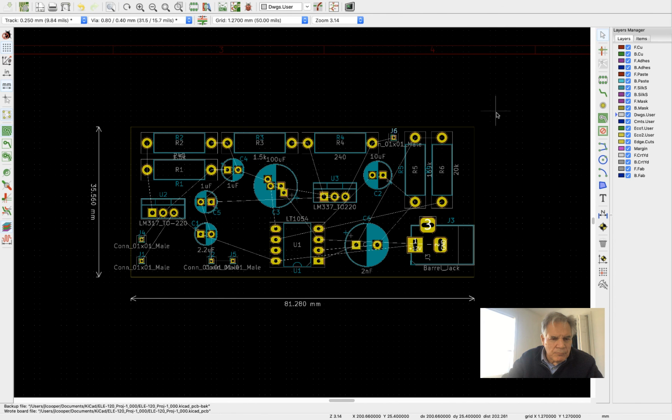And what I'd like you all to do, I'll post this as a homework, is get to this point, or not necessarily this point, but a point where you've done the best you can to eliminate crossovers and get something that looks like it could be routed with double-sided routing. That is, keep the number of crossovers low, and you'll be able to route it.